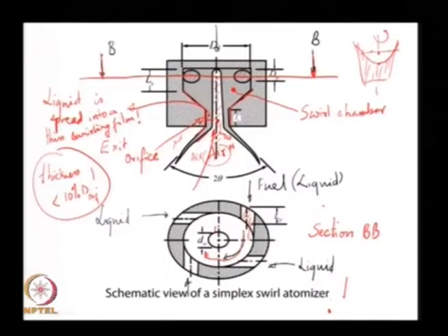The tangential velocity is what is responsible for the liquid sticking to the walls, creating a very thin film. So, I can create as thin a film as I want for whatever be your flow rate by changing the design, the diameters of the tangential injection orifices, and the number of those orifices. This is an added degree of freedom I did not have in the diesel injector.